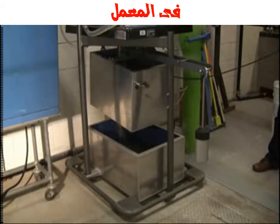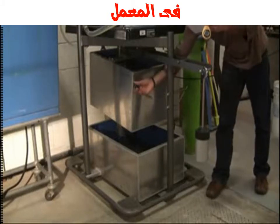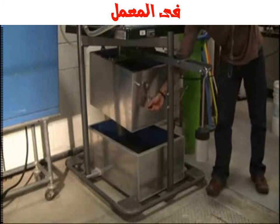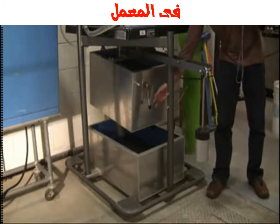Next will be a description of the discharge measurement. Make sure you have a timer at hand. Look into the weighing tank and try to understand the mechanism of the stopper. By turning the lever on the front of the tank counterclockwise in the vertical position shown, the drain at the bottom of the tank will be plugged.